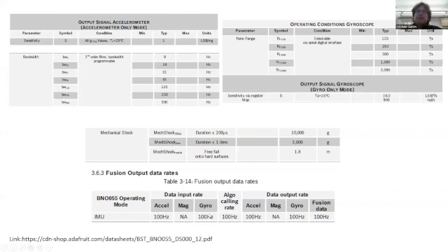And it's up to you to figure out, is that fast enough to measure the vibration spectrum? For instance, if you're trying to do transient vibration characterization or transient shock characterization, is 100 hertz going to be fast enough readout to fully characterize the environments that I'm being subjected to? Or am I going to be missing some key readout frequencies, key excitation frequencies?